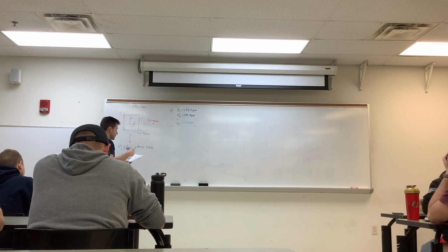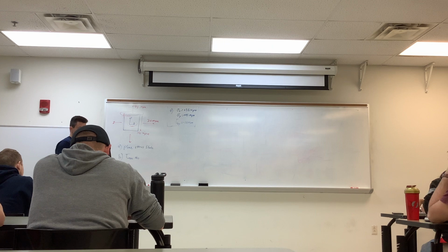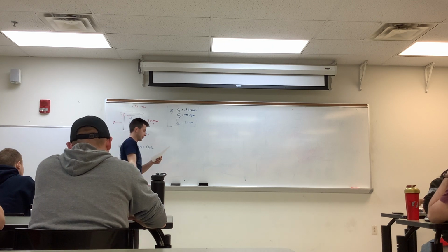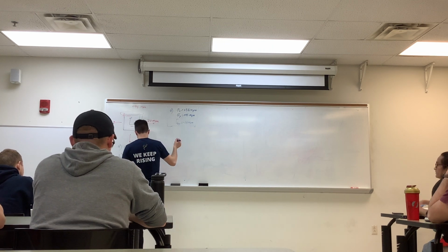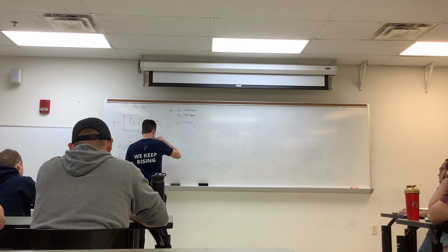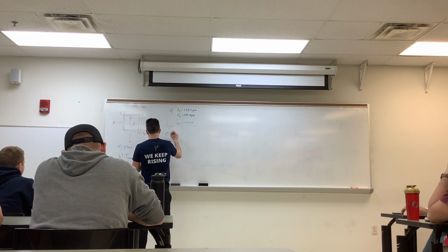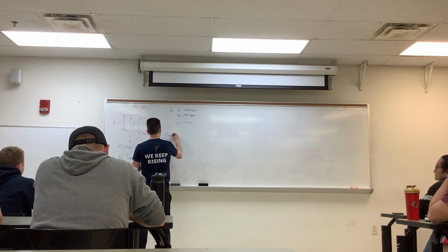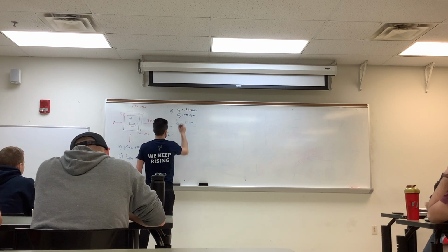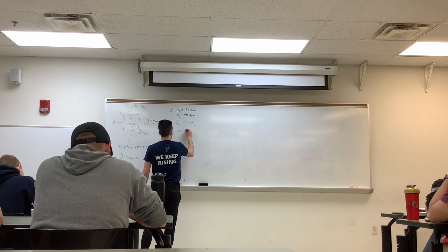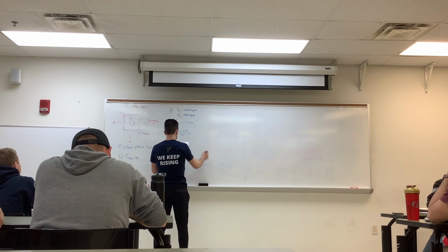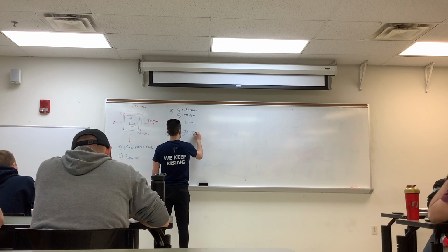So next step, what we can do is start trying to find our absolute max shear. I'm going to take the average between the two just to get what would be our center, or point C, between these. So we have our sigma average, which is 30 plus 45 divided by 2, giving us 37.5 MPa.